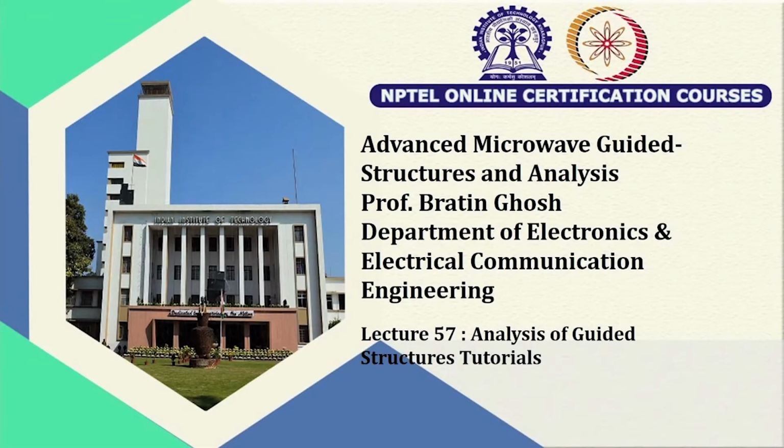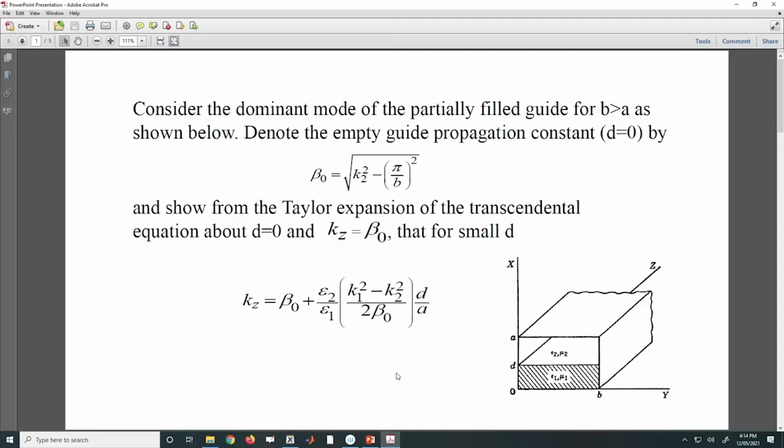Hello everyone. Today we will solve some numerical problems on partially filled waveguide. So, to start with, this is our first numerical problem and it states that consider the dominant mode of the partially filled guide for b greater than a as shown below.